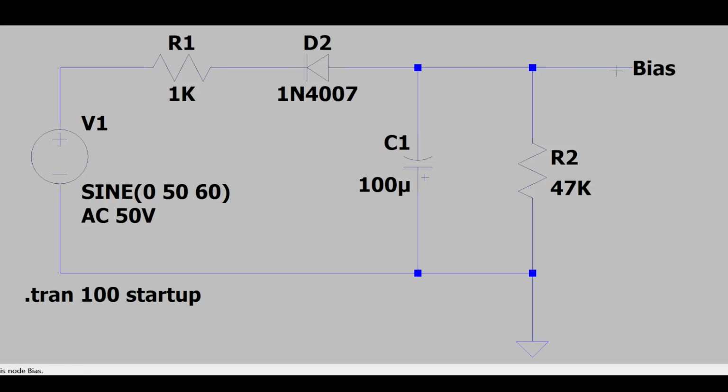Again, you will potentially run hot because that will only limit you down to a hotter bias point, whereas the voltage doubler will allow you to go colder and potentially not have to bias your tubes above 80 to 90% dissipation.